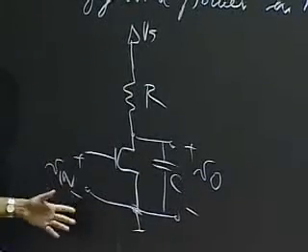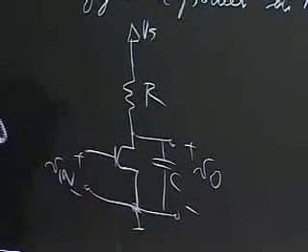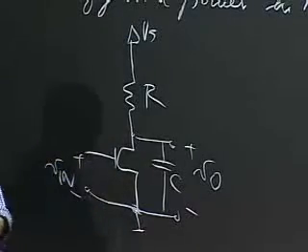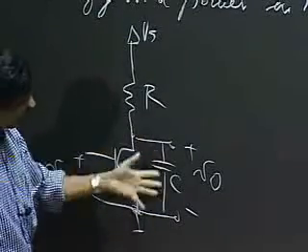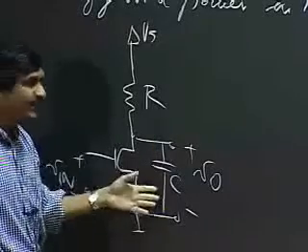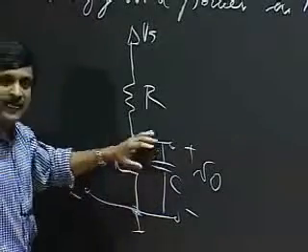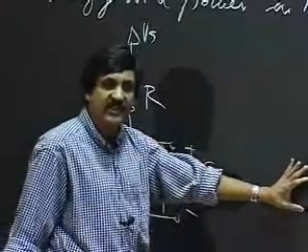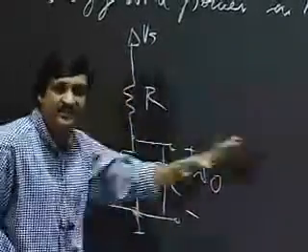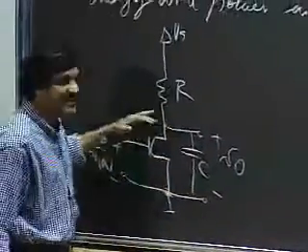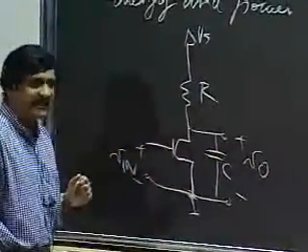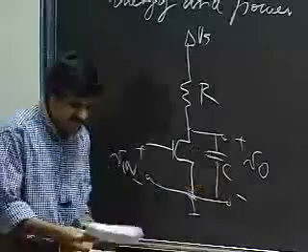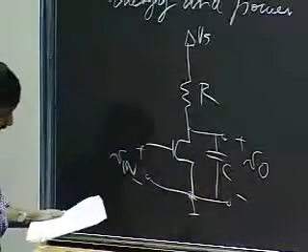It could be a square wave. It could be some sequence of ones and zeros. And this is the inverter that we all know and love. And here I've stuck in a capacitor. This capacitor is meant to model the input gate capacitance of whatever this inverter drives, plus any capacitance of the wire leading up to that gate, and so on. So it's just a lumped capacitor that I've stuck on there.